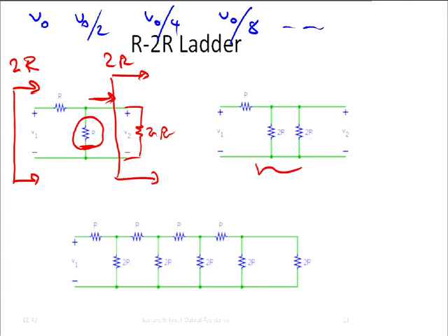But now comes the trick. This resistor I actually built, but the second one is something else. What is the second resistor? Well, I want to cascade stages that divide by 2. They look like a resistor of value 2R, right? So I'm going to replace this resistor here with a whole stage like this.